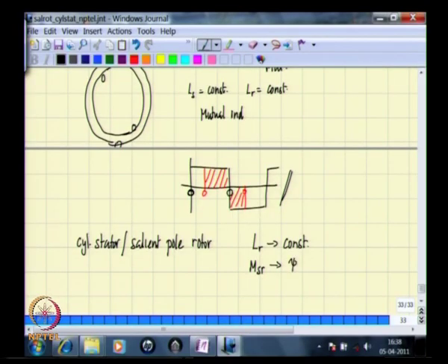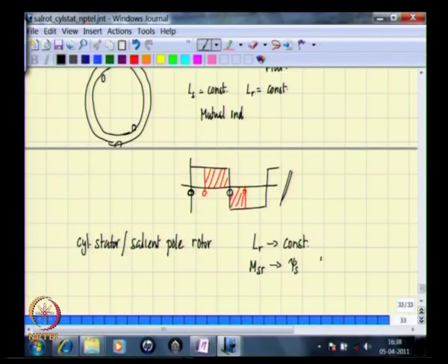Having known the expression for the Fourier series, you go about determining the flux linkage on the stator, and thereby we could get an expression for the mutual inductance, which consists of a fundamental term and several harmonics. And we said that by and large in most machines we have a sinusoidal variation of the mutual inductance, and therefore the fundamental component alone would be sufficient.